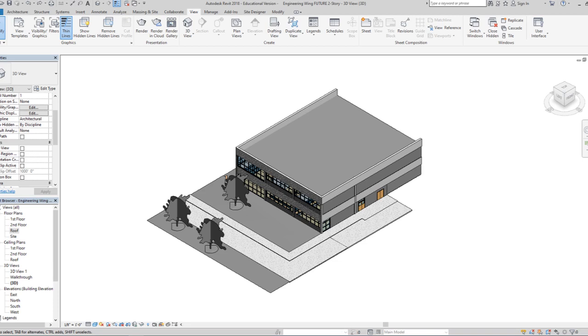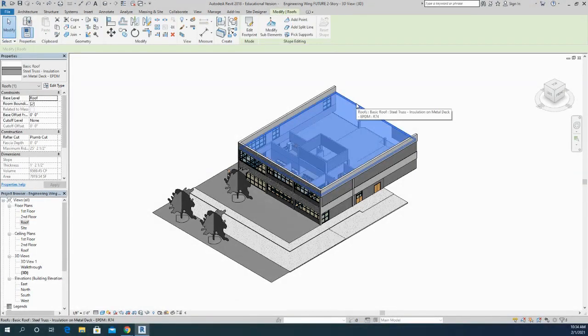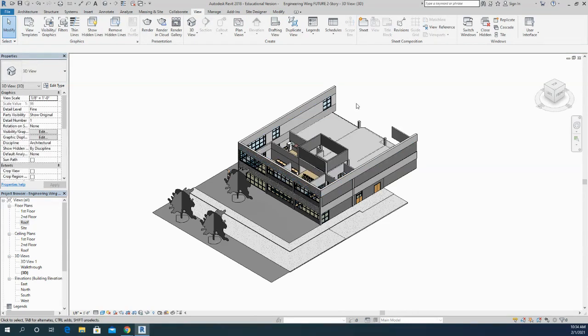In this tutorial, we're going to take a look at how to create a sloped roof, calculate its volume, and also create a floor and calculate its volume using the extend into core option. So we're going to start by just clicking on this roof and hitting the delete key to delete it. And we're going to create a floor in this upstairs little tiny square region first.